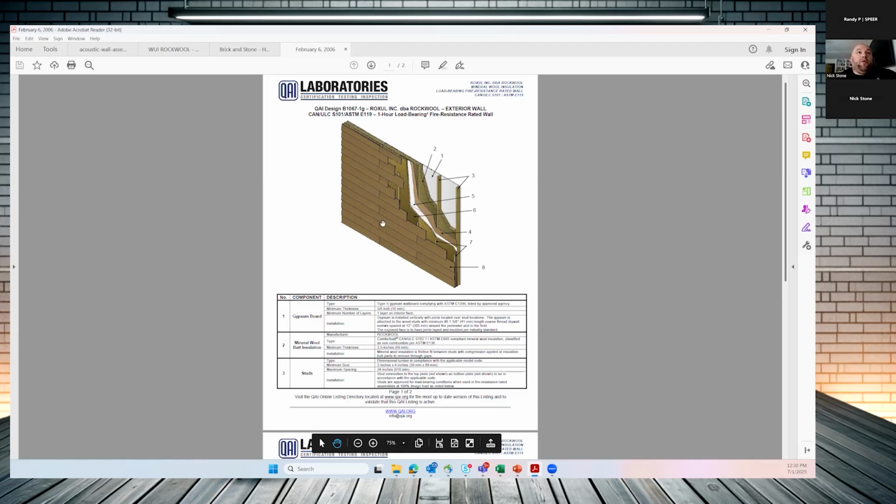So within this wall design here, where we have 1.5 inch of Comfort Board on the outside, and then we have whatever the makeup is between the siding, WRB and sheathing, and then you have a Comfort Batt material in the wall cavity. This is going to give you a 1 hour exterior wall. So if you're in those WUI areas, if you're building closer and closer together, this gives you a lot of flexibility within that fire safety category to help really add that documentation to the way you're designing by making sure we're having these great non-combustible materials.